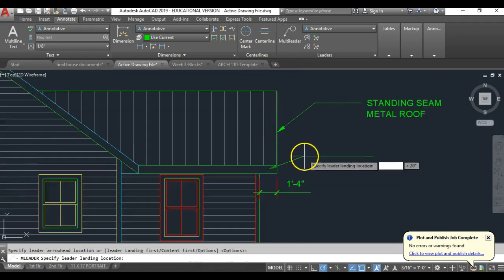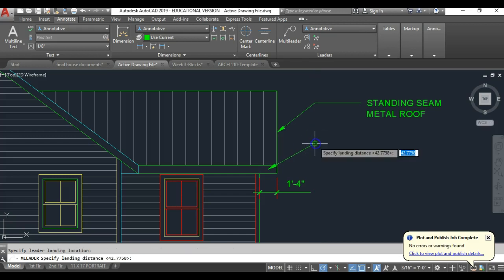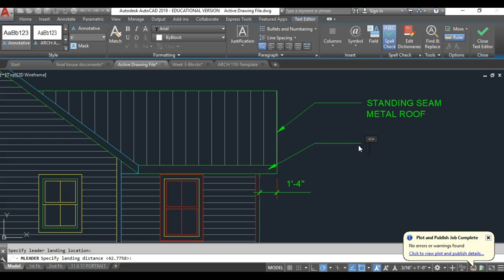Now the thing when you're doing dimensions is you do want to make sure that these points are aligned. So I'm just going to hover over that point there to activate a guideline. We can see when I pull down, if I keep my mouse careful, it's going to make sure it's in vertical alignment and approximately the same angle. So I'm going to click there, and then the same thing as the end of this line also wants to be aligned. So I'm going to hover up over there and pull down to draw an alignment before I type in fascia.